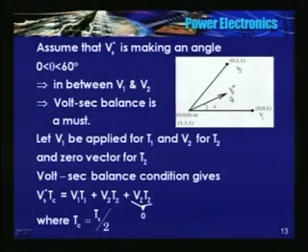It looks like the frequency of operation is less than the rated, therefore the magnitude of the space vector is also less than the rated, and it lies in between sector 1 and sector 2, or it is in sector 1.